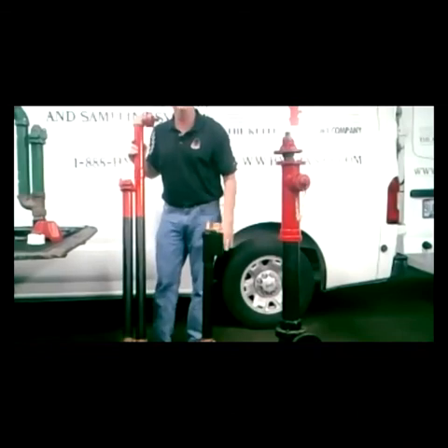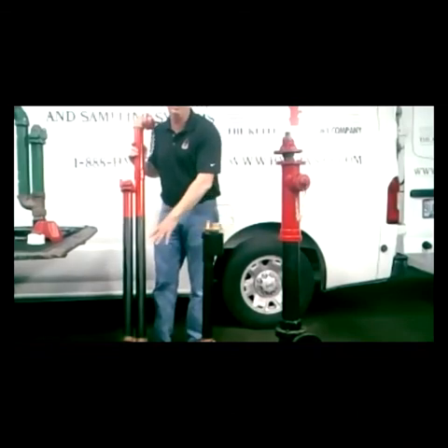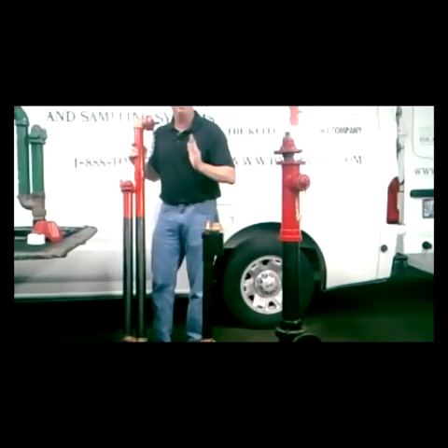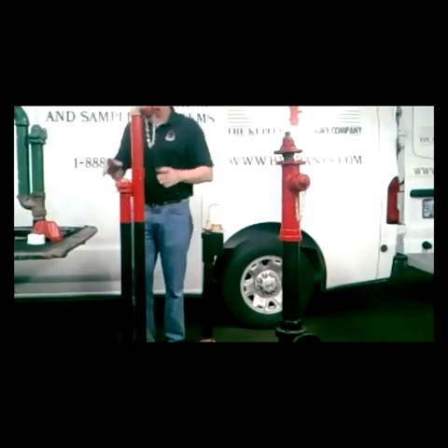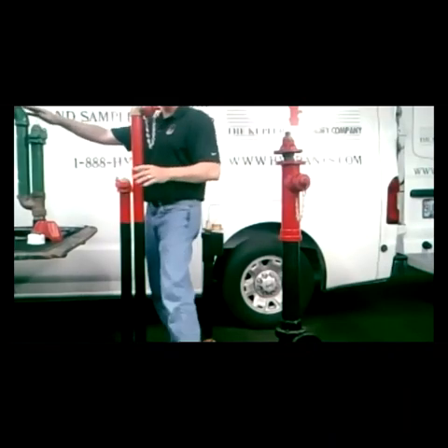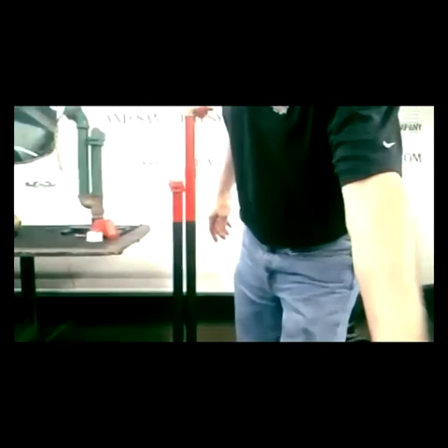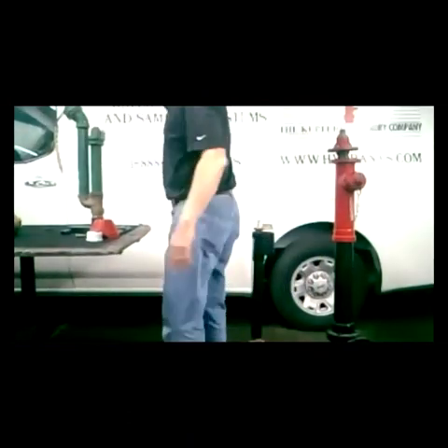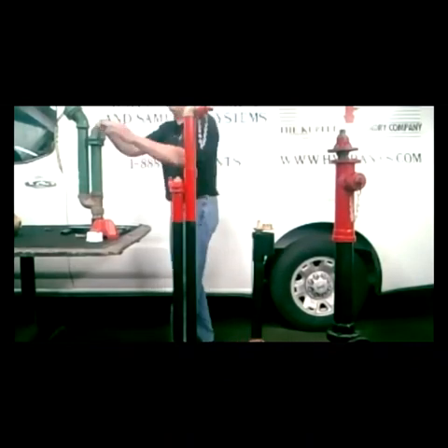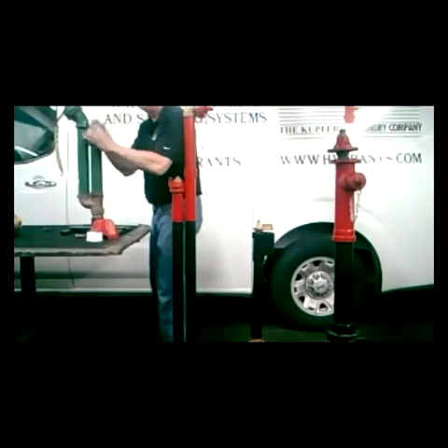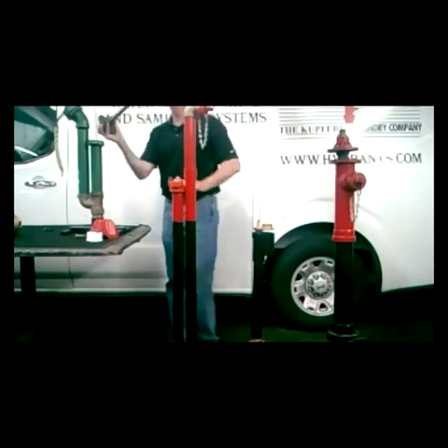And we can do up to a 2-inch MJ on these. So either a 2-inch IP, vertical or horizontal, or we can do a 2-inch MJ horizontal. To do maintenance on this and the 78, which is the green one next door here, this is the below grade version. This one fits in the meter box. This one's above ground. Again, to do maintenance, I turn the water off, 2 bolts, I take them out. Again, I can pull the whole guts right here.